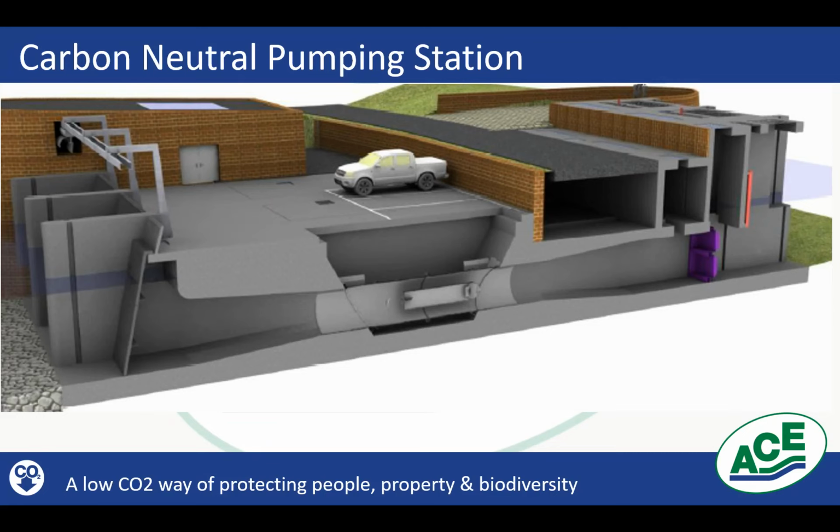A lot of the time, they're not actually pumping. They're operating through gravity. So most of them have one or two or several gravity sluices, and they try and, at low tide, let as much water out to the sea as possible through the sluice. Of course, it's completely free. You don't require energy. Makes complete and utter sense to only pump when you need to pump because either there's a high tide and you've got too much water in your drain or whatever the circumstances might be. But while the tide is low, get rid of that water as much as possible.